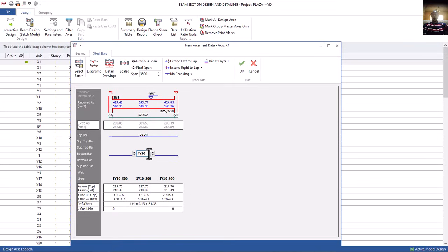Can you see now? So it's now left for you as a structural engineer. Do I want to use a lesser number of bars with a higher diameter of reinforcement, or reduce the diameter in terms of quantity? In looking at this, quantity increases but diameter reduces. In this case, quantity reduces and diameter increases. So it's now left for you to make your choice. Is that okay? Coming to this place also, I can decide to make this one 16, then 3. Can you see it now? So that's 3Y16 at the top and also 4Y16 at the bottom.